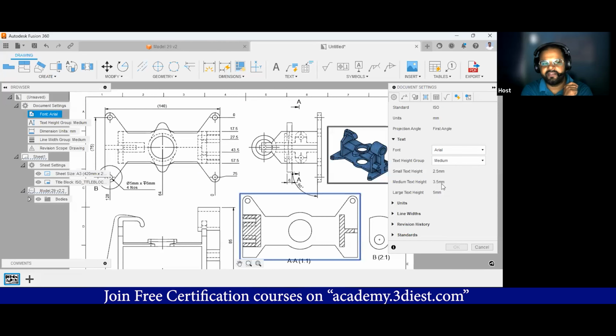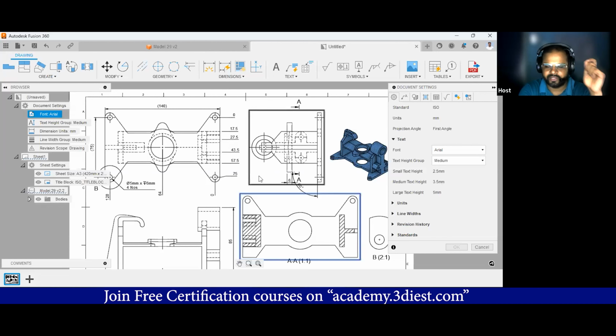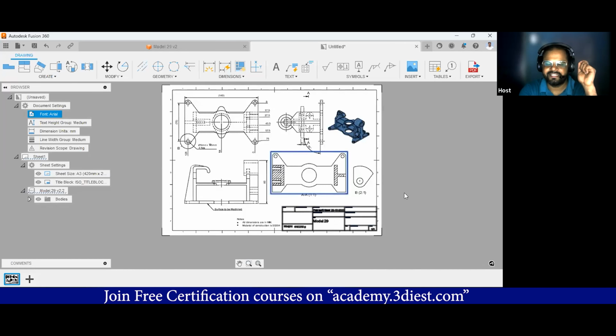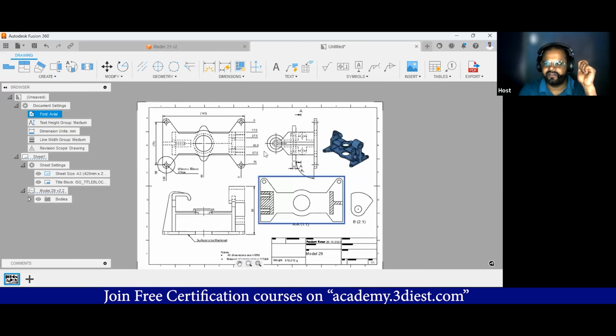You cannot take any of the text or sizes less than 3.5. If it is less than 3.5, there will be a human error in reading your drawings. So make sure that everything that you are considering on your drawing, any text, any dimensions, any feature, any annotations, has to be either 3.5 or higher than that for A3 size paper. Just keep it in your mind. And by default, Fusion 360 for A3 sheet size is already providing 3.5, so that's really great and also saving lots of time.